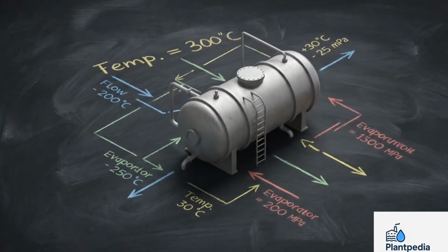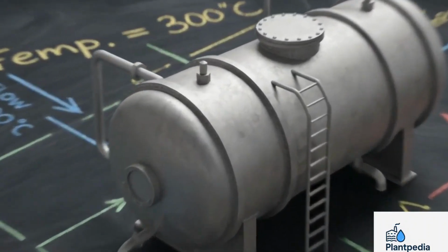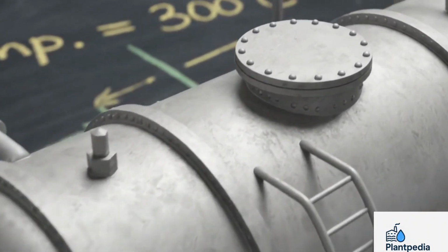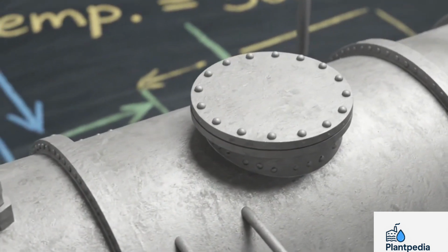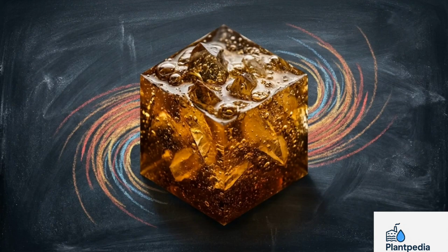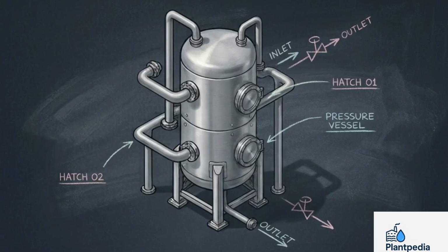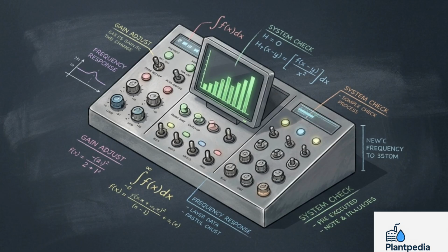When an industrial evaporator is running at full capacity, operators face an immediate problem. You need to know exactly how thick the liquid has become, but the entire process is sealed inside a massive churning steel tank. You solve this by measuring the boiling point elevation, or BPE. It is the most reliable, measurable indicator of brine concentration available to an operator.